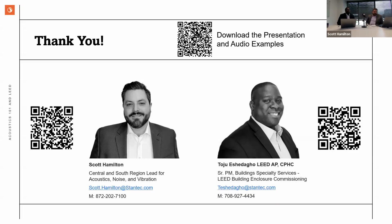So that's an interesting dynamic because you have some things going on. If you talk about a glazed CMU, that means you've got a product over top of it that takes a lot of the frit away from it, and it makes it really smooth. So that actual face becomes an acoustically reflective surface, more so than unsealed CMU, which has a little bit of acoustic absorption to it.